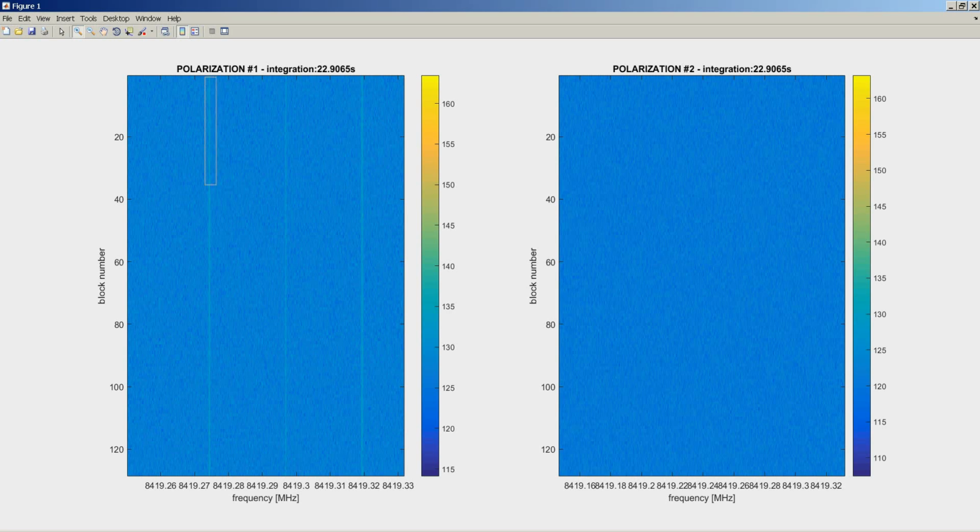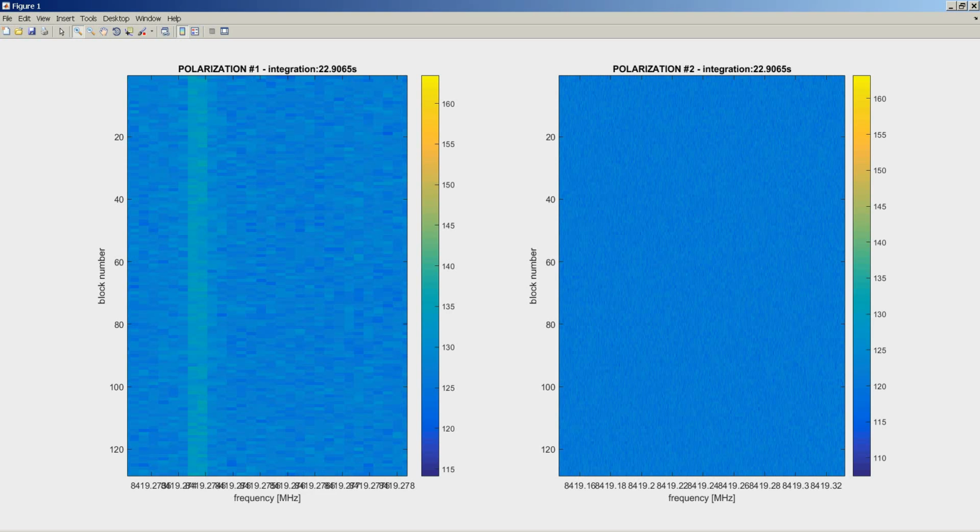Another reason why there are 3 peaks is simply that the signal that is transmitted towards the Earth from Voyager 1 is a BPSK modulated signal. And this BPSK signal is pretty wide band. And a common practice in communication is to include a few very narrowband features in the signal to make it simply easier to lock your local oscillator to the data and make it easier to detect as well. So that's good for us. It's been easy to detect.